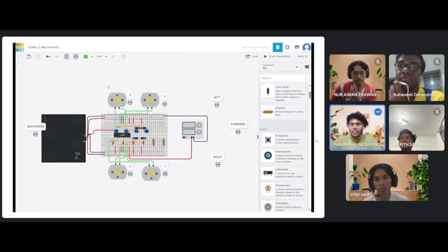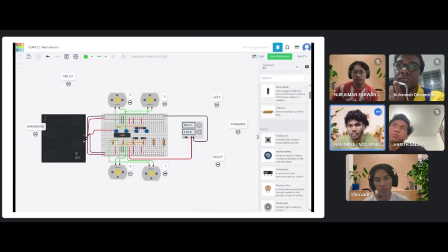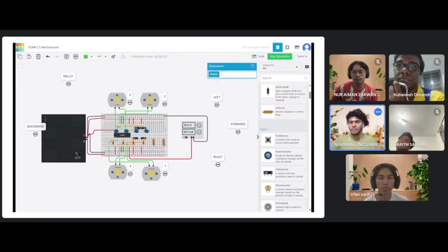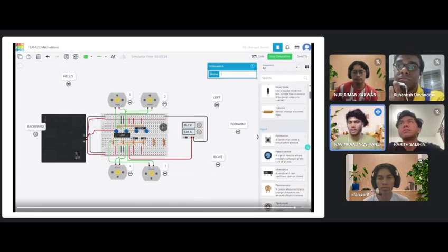As you can see, once the simulation is started, you can clearly see I've shown where is forward, where is backward, and the location of the motors. As you can see, this is a four-wheel drive which has been modified. When I put in the perfect 30 volts and also 1.31 amperes as what was told by Irfan, we can see that all the four motors are running. At the same time, using the switch, we can change the movement to clockwise or anti-clockwise of the motor. This actually helps to run the motor smoothly. You can clearly see the video is running well and the simulation works.